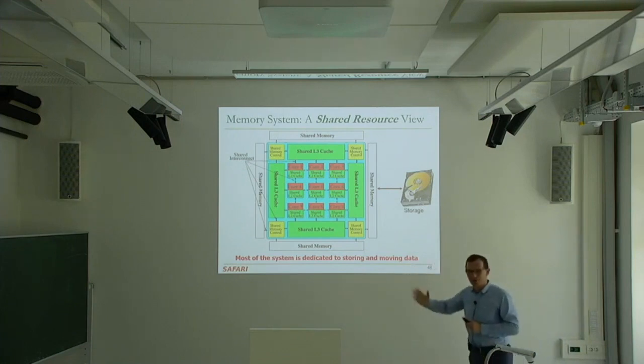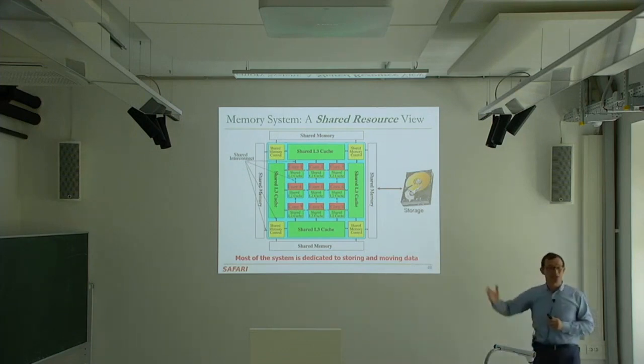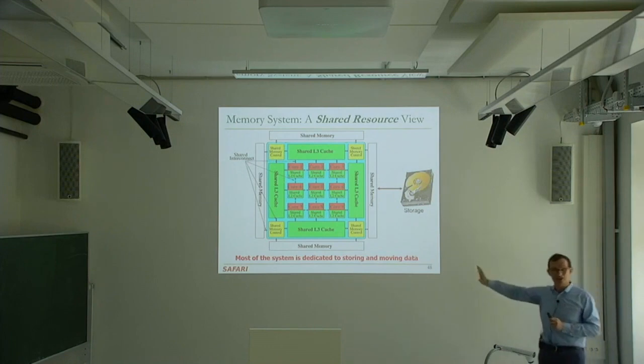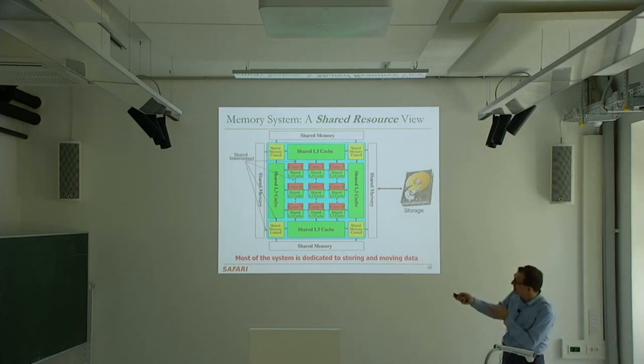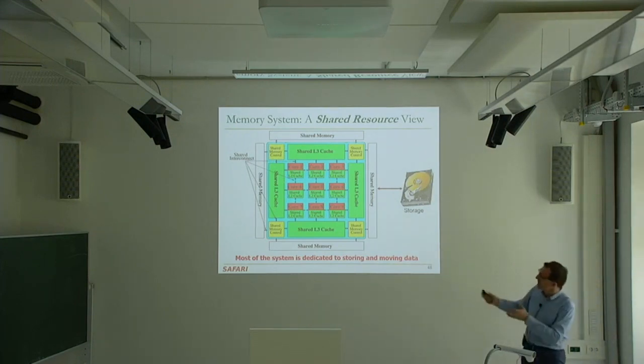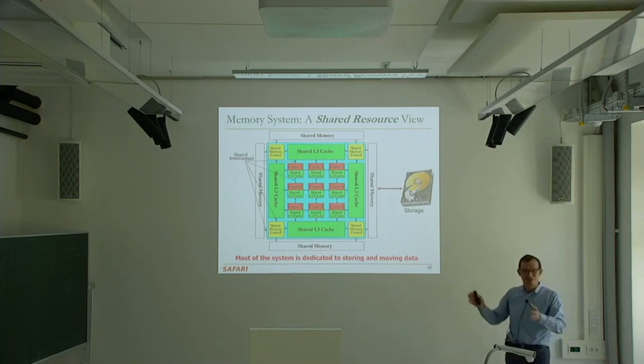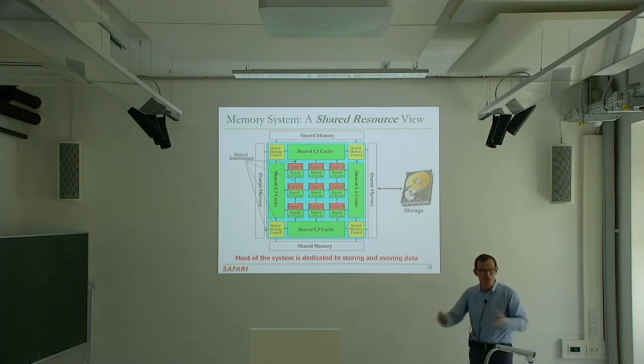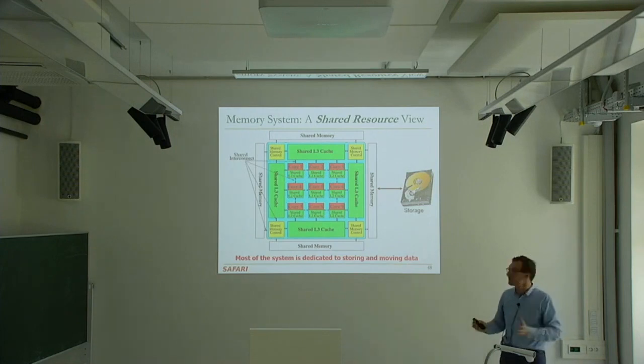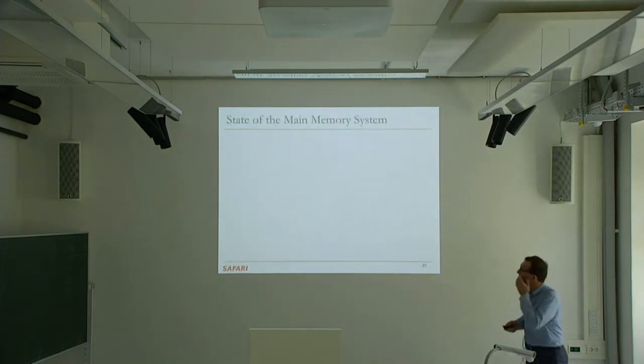If you actually do the calculations on different chips, you could go up to 90% of the resources dedicated to storing and moving data. Because if you look inside these cores, well, there are L1 caches over here. There are registers. And they're basically there to move and store data. Computation is actually not a big problem today.